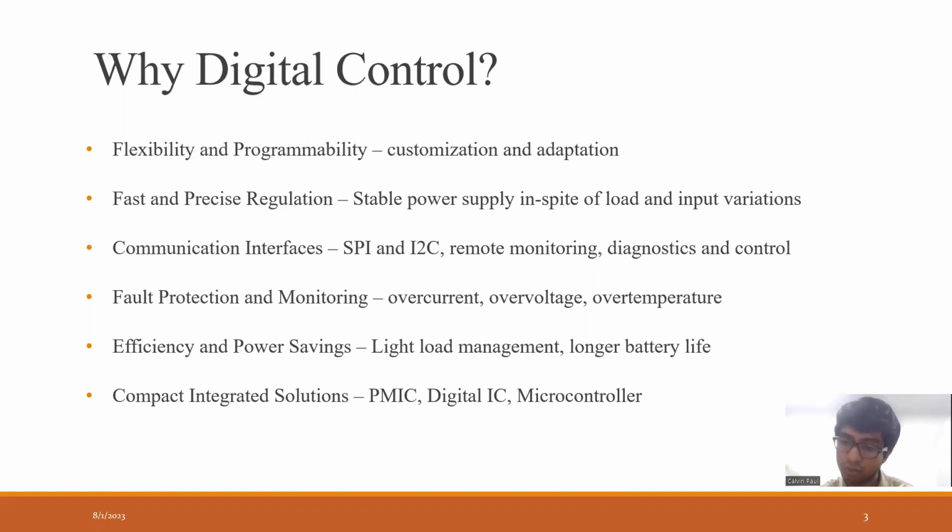And then when I get some sort of notification or when I start using it, I need to increase the power output of my converter such that it can perform the function. So for that, we can have power saving. At a light load, when it is not required to be used, it can work in a dim power. But when I'm watching a movie at maximum brightness, it will require more power. So based on the requirement, it will dynamically change how much power is used. That is something which can be done using digital control.